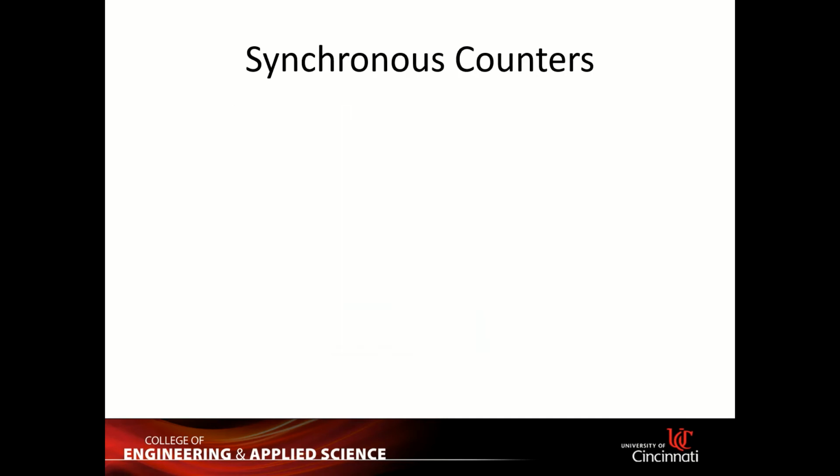Okay, so the difficult one is over. Now is the easy one. Synchronous counters. Remember the first example we went through? Basically, we have the state diagram and we go through the whole process of building a state machine. It's not some trick that you have to scan from one column to another column. It's more intuitive. But the only tricky part, similar to registers, is that you have to make sure all of the flip-flops are synchronized with the same clock. Otherwise, all of your operation is going to be totally messed up. So the key thing here is that the clock and the synchronism of the clock and all of the flip-flops have to be controlled well.